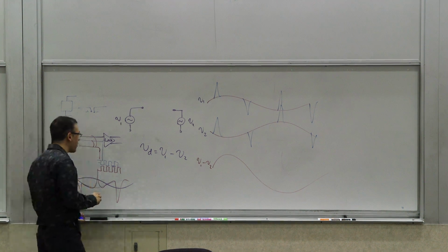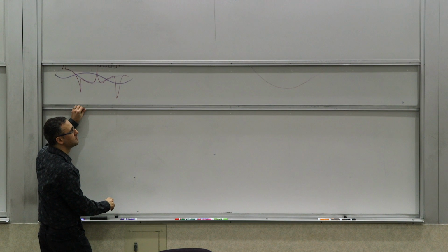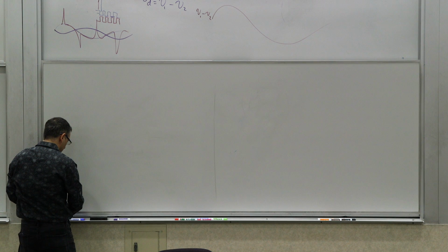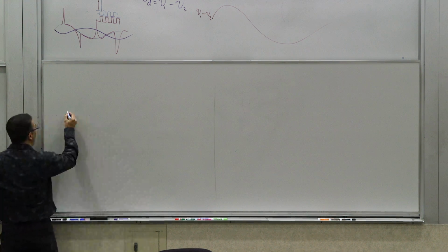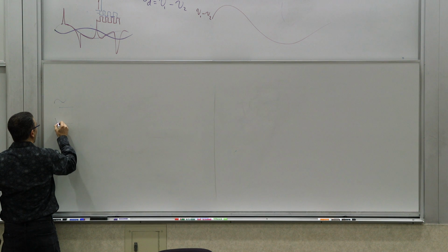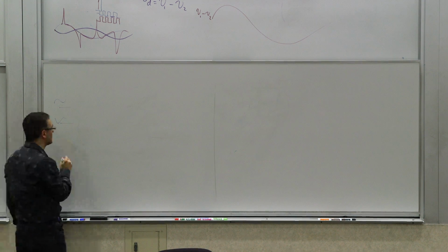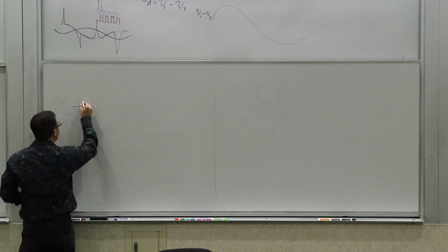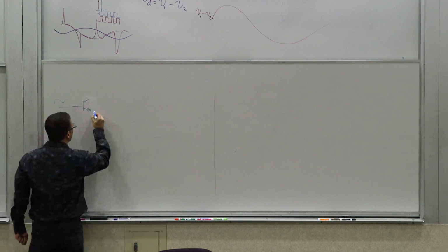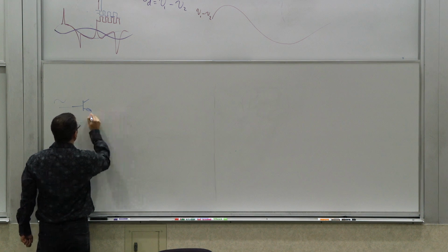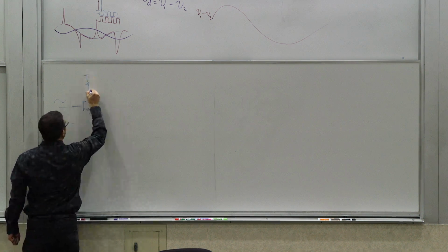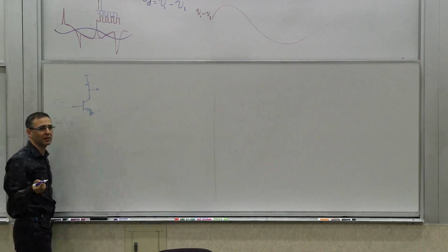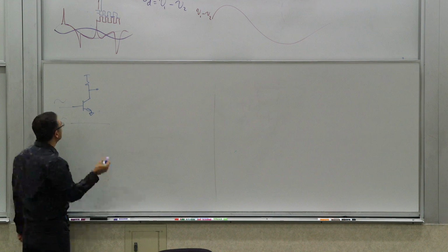So what is the simplest form of making that amplifier? We can do a variety of different versions. So let's say I have two signals coming in that are going in opposite phases, and I want to amplify them and keep them differential. So what do I do? Well, you can make an amplifier like this. Let's make a common emitter amplifier or common source amplifier in a MOSFET. Let's say we had something like this.